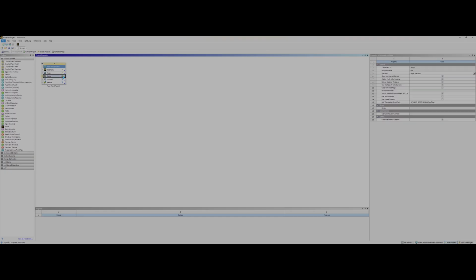All right. Now we could go to setup. I'll use double precision, and then in here, I'm not going to run all 32 because this will make my computer run extremely hot. So I'll run 24. With meshing it was fine because it was pretty quick. But for here, in the setup, this will be sustained over a long period of time. Maybe sometimes it could be an hour, although for me it would be like 15 minutes. But depending on your case, if it finishes in an hour, then yeah, good luck. So this will sustain your course. So click start.